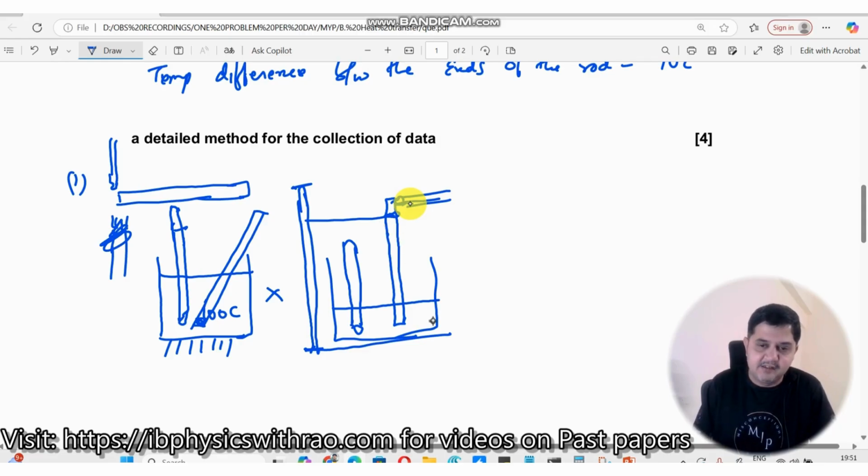Okay, now we have decided all this. So we are going to find out the initial temperature. Every time I need not find the initial temperature because I am already boiling this water over here. So the initial temperature will always be 100 degrees Celsius. And what I can find out is what was the temperature of the rod before I dipped it into the water. Then after dipping it, I'll start heating it and see to it that the water continuously keeps boiling. That means I'm providing a continuous supply of heat energy, so that the water is always maintained at 100 degrees Celsius, and then it transfers energy to the rod, and wait until this end of the rod becomes